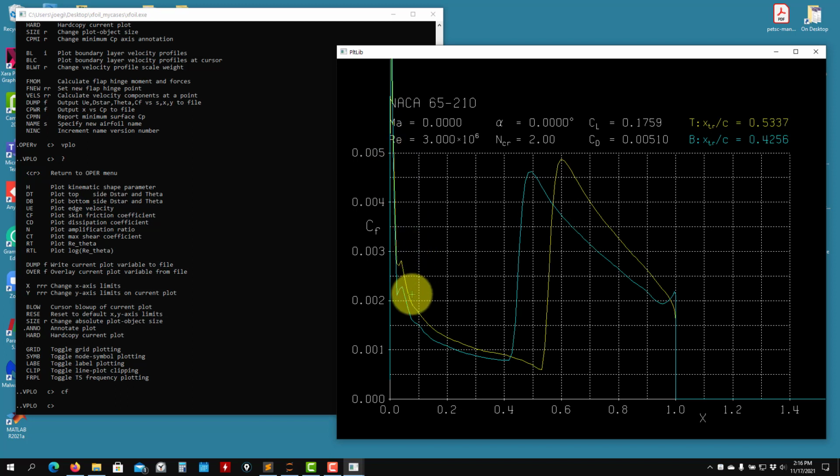See here that you have a laminar boundary layer, then the onset of the turbulent boundary layer, and then it's turbulent. Here you clearly see that when you have a turbulent boundary layer, you have more skin friction. But it might happen that your pressure drag is lower, so the contribution will be positive. You will need to analyze that. So you have many plots here. It's up to you to choose which one you want to use. I like to use this one, but you have it there.